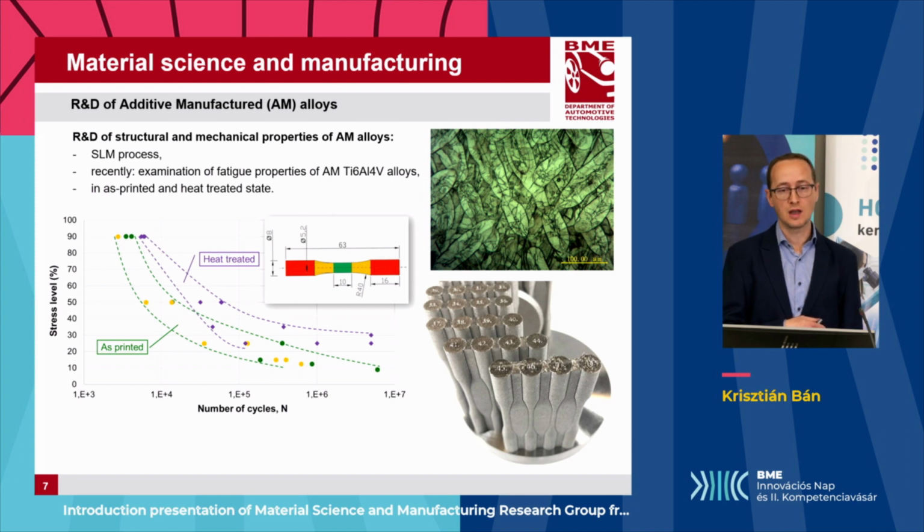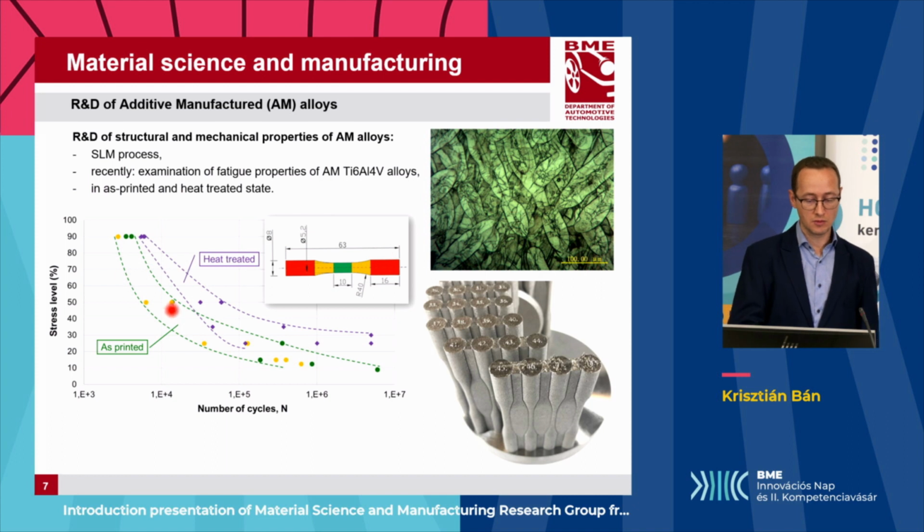These samples are made by selective laser melting, and recently we examined the fatigue properties of additive manufactured titanium, aluminum, vanadium. Here in this figure, the Wöhler curve was plotted of titanium, aluminum, vanadium in both states, which is as printed and the heat-treated state.